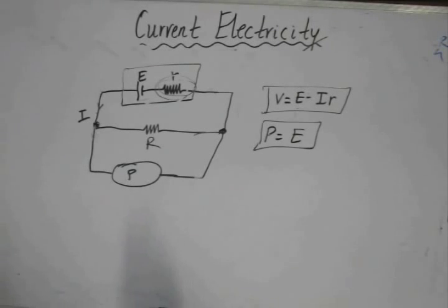But there is still one disadvantage of the potentiometer: the device is not portable in comparison to a voltmeter. The advantage of a voltmeter over a potentiometer is that it is more portable. It's much easier to carry a voltmeter than a potentiometer. But if we want accuracy, we can use a potentiometer instead of a voltmeter to determine the value or to compare the EMF of cells.